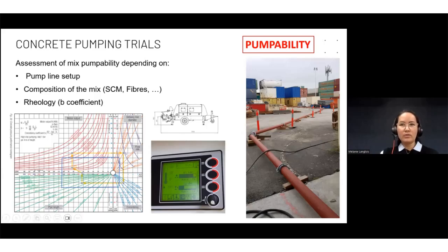Then the issue with pumpability. I often hear that the concrete is very sticky, that we can't place it, that we can't pump it. And I have workforce and supervisors on site struggling a lot with high SCM mixes. So what can we do for that? Ahead of using the concrete on site, we can do some pumpability trials. You might think it's going to cost a lot of money, but you're going to save money later by making sure that you're in control of the concrete that you're placing.